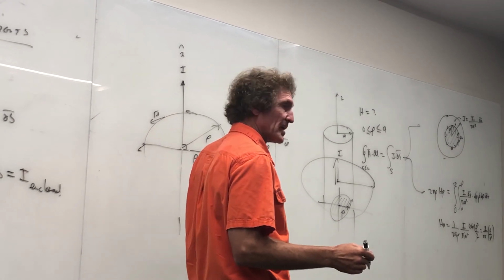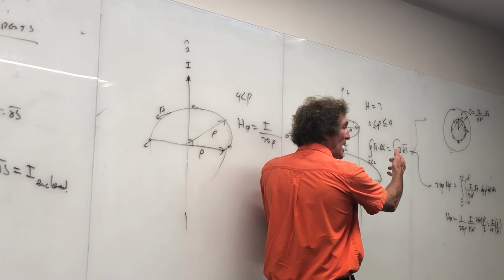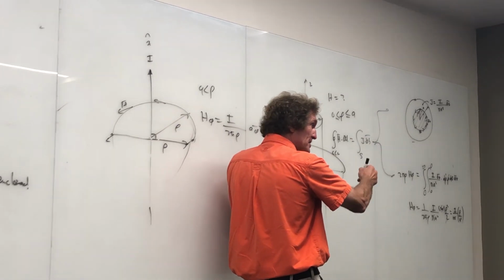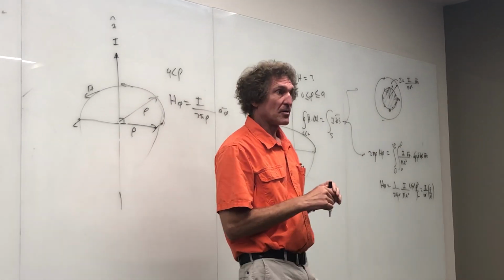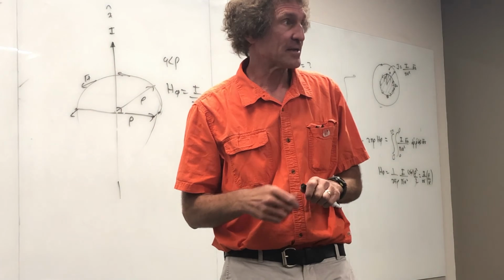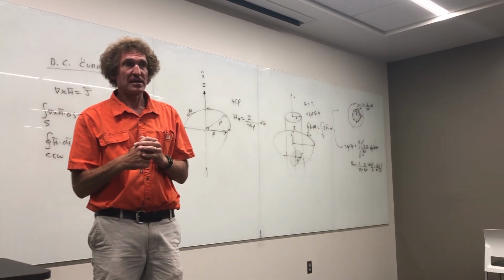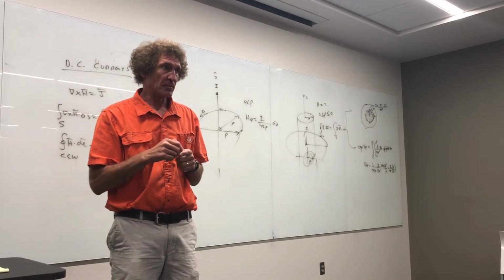And that's the nice thing about these problems. Now, if at some point there was a thicker pipe that had the same amount of current but in the other direction, then when you get outside where that pipe is, the H field would go to 0. Right? And that would be like a coax cable effect. That's why coaxial cables don't really have any H field outside the actual outer, that woven aluminum thing.